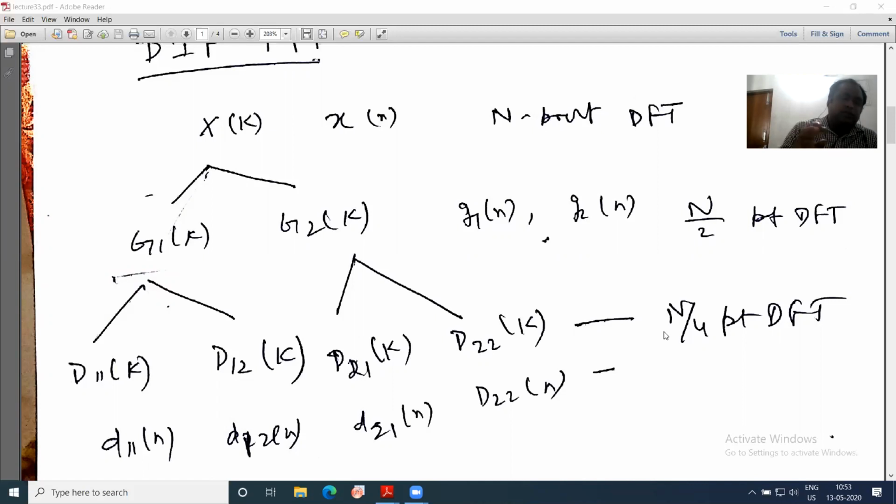First point is that if I say two, one is DFT and FFT. Difference is DFT has a higher computational complexity, FFT is having lesser computational complexity. This is the difference between DFT and FFT. However, result of DFT and result of FFT are same. Now, if I come into the two algorithms, DIT FFT and DIF FFT, both are FFT. Therefore, computational complexity reduction is the major target of these two algorithms.